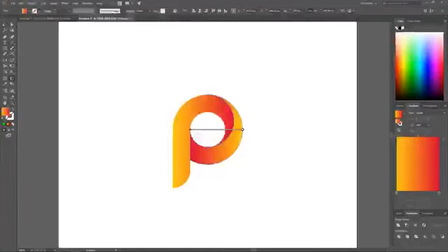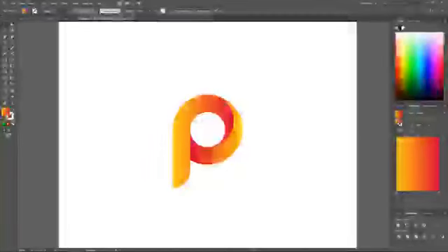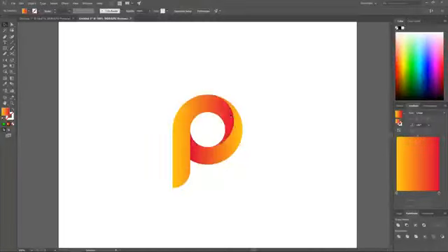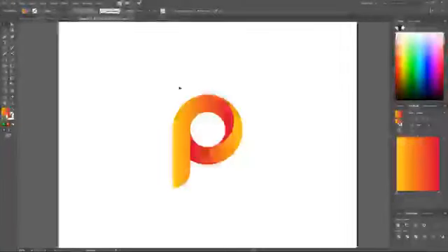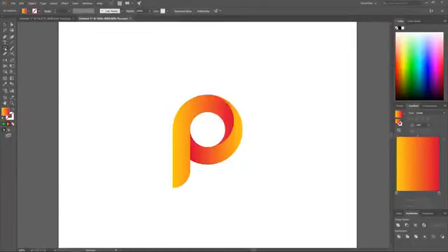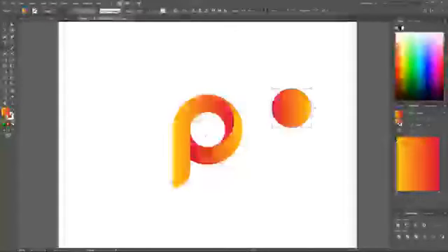The only last thing to do would be, let me grab the Select tool. The last thing to do would be to put a little bit of a shadow right here, so it looks like it's casting a little bit of a drop shadow over this. To do that, let me click and hold on the rectangle so I can grab the Ellipse tool again. And I'm going to create another ellipse. I'm going to hold Shift and Alt and click and drag to create a perfectly round ellipse.